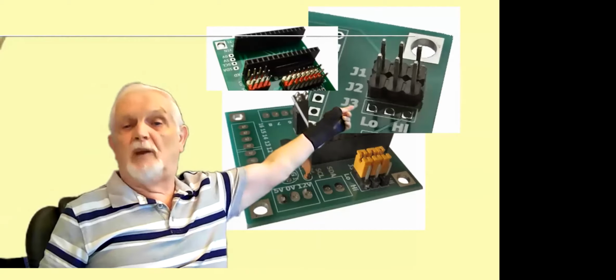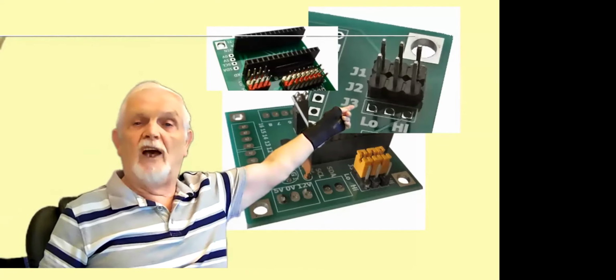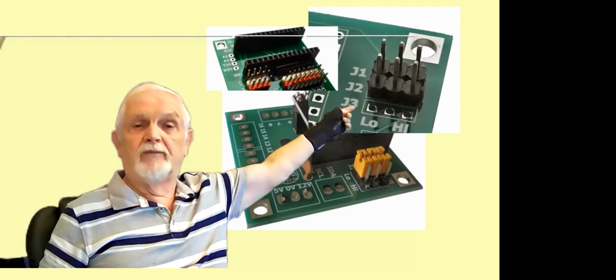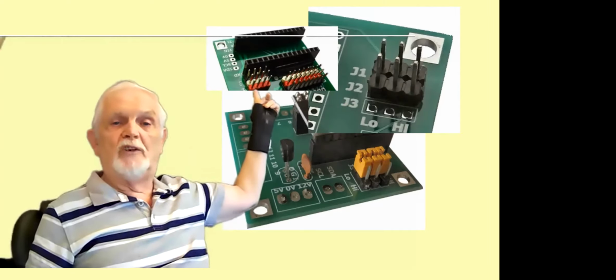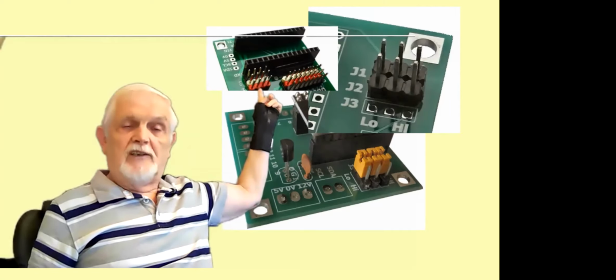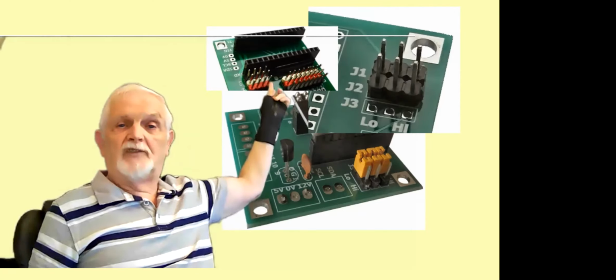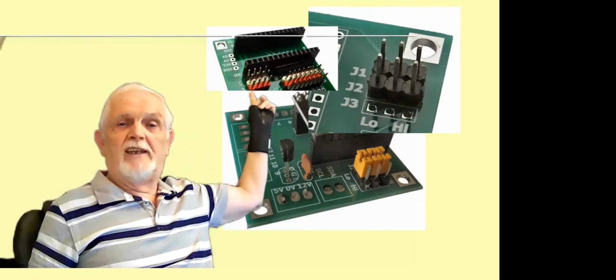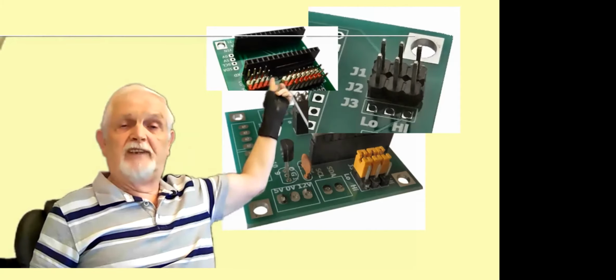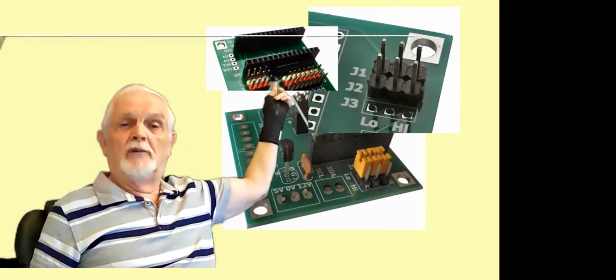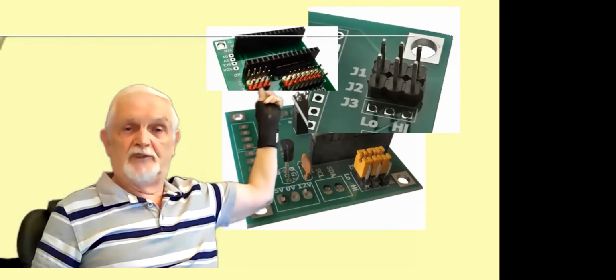So there's 3 sets of pins. They can take either high or low. In terms of the output modules, there's 16 different addresses you're allowed to have. So you've got 4 pins. In other words, a 1, a 2, a 4, and an 8. Add them all together, you get 15, right down to 0, which is your 16 different options.